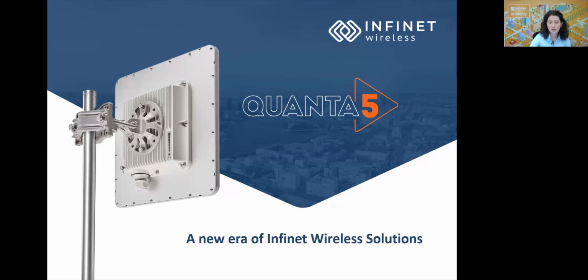Nick is saying that having a single radio means it cannot move channels without performing channel availability check. Yes, it constantly performs channel availability check, but it is only done when no data is being transmitted in a very short frame time. So you will not lose connectivity with the unit, and you will also not see the link interrupted, because everything is performed in between transmissions, and you will not notice any interruption. It will not affect the throughput in any way.